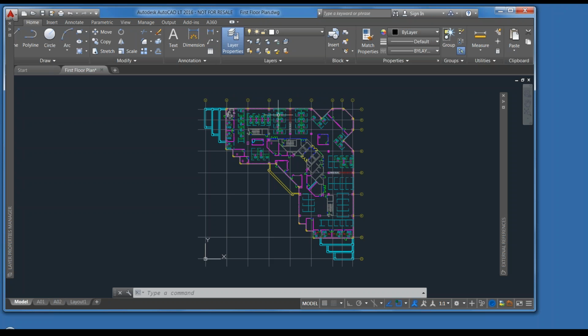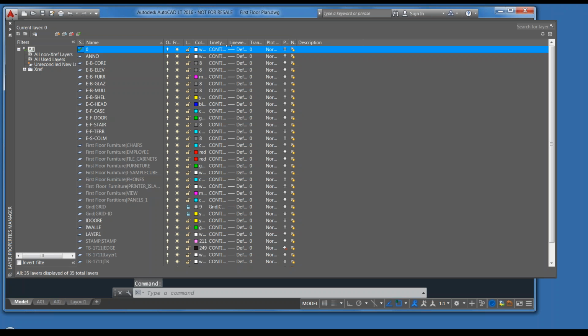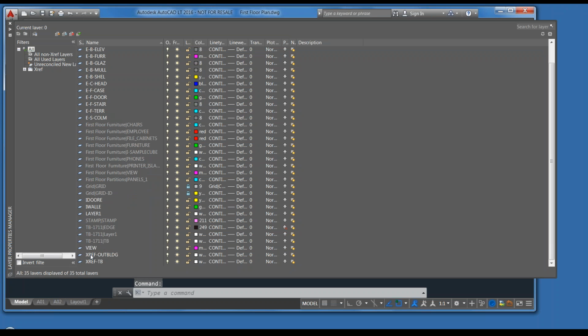This is where locked layer fading could be useful too, which brings up another tip or idea that a lot of people do, which is they have a dedicated layer for X referencing. The advantage of that is you can lock that layer or fade it or just manage it more readily by it having its own dedicated layer.